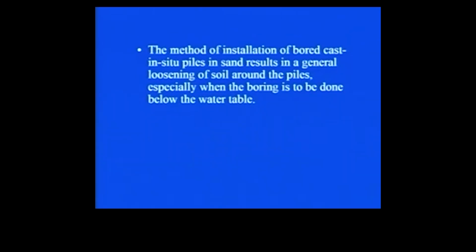This aspect we have already seen, although it is bored cast in situ piles, in which you create a borehole or a void and then you install the pile in that. However, in case of sand, while you create that void, in that particular process, the soil around the walls of the borehole gets loosened. So, because of that the problem occurs.